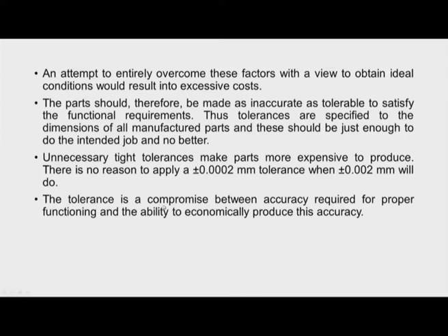And then we should understand that the tolerance is a compromise between the accuracy required for proper functioning and the ability to economically produce this work to produce the accuracy. We should always understand that while specifying the tolerance, the need should be satisfied, as well as we should consider the manufacturing aspect, so that the product can be produced with economy.